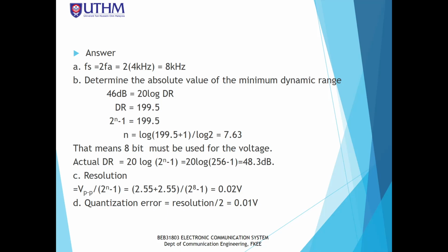The dynamic range is given as 46 decibels, the minimum dynamic range. And dynamic range in decibels is 20 log DR. So 20 log DR is 46 dB.